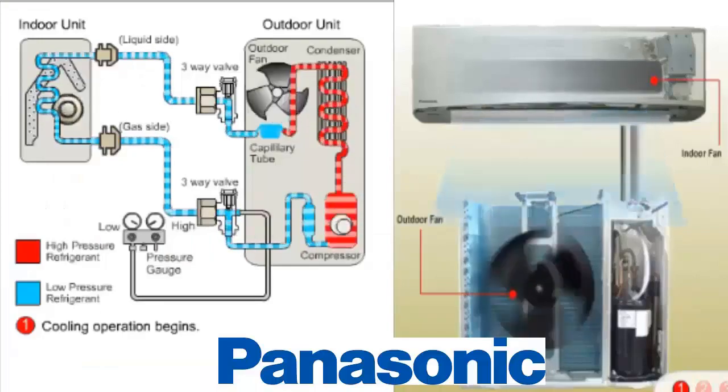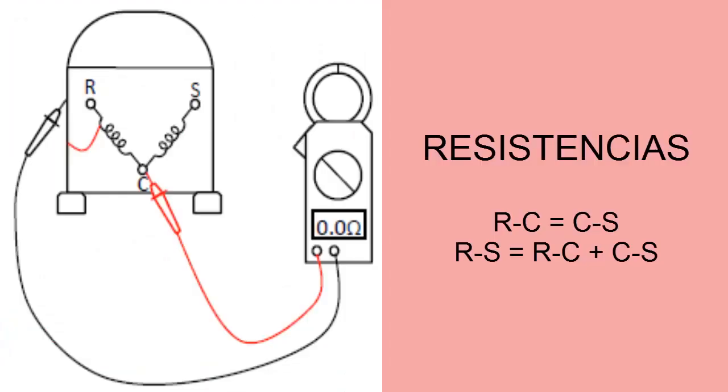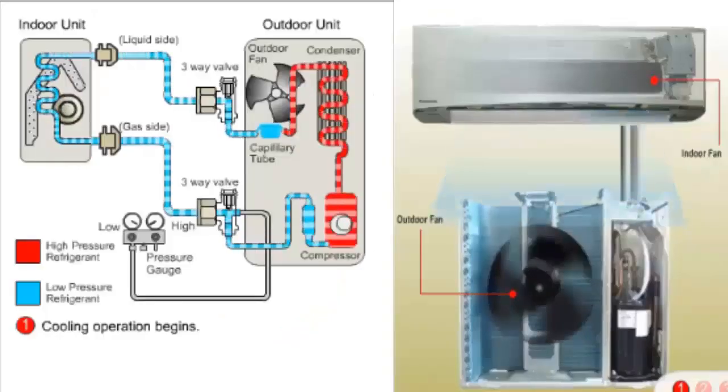B. Electrical issues with the compressor's internal coils. Measure their electrical resistances by disconnecting them electrically and using a multimeter. These resistances should have the same value, and should never read infinite or zero. Additionally, the compressor coils must be isolated from the compressor housing.